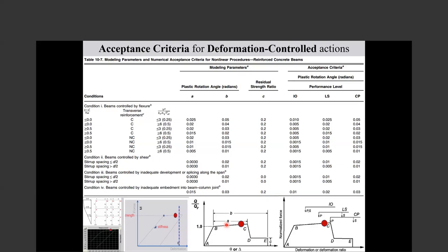For example, if you use the approach for existing buildings, you can omit the need for the R factor. But some codes that use nonlinear analysis say that they let it be used just for the optimization of design. In a way, they say that at the end you should check with the linear methods.